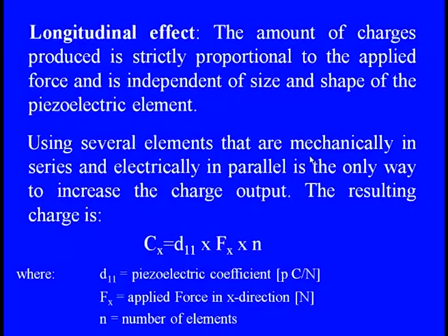So we can simply use a number of elements to which we can apply these forces and generate electricity. Using several elements that are mechanically in series and electrically in parallel, because the charge generation is perpendicular to that part, is the only way to increase the charge output when the longitudinal effect is used.